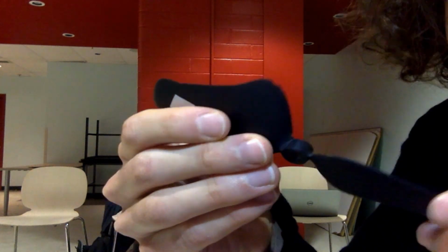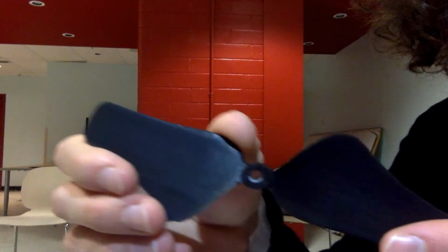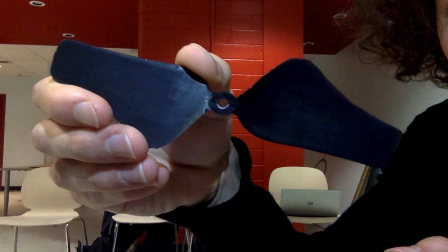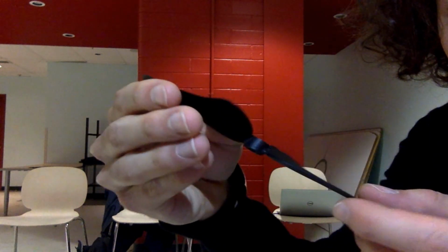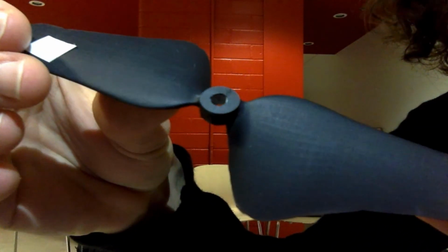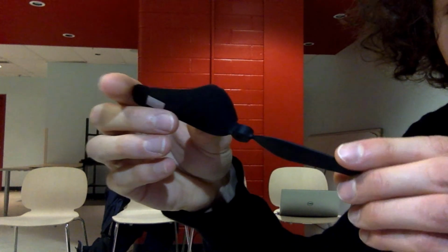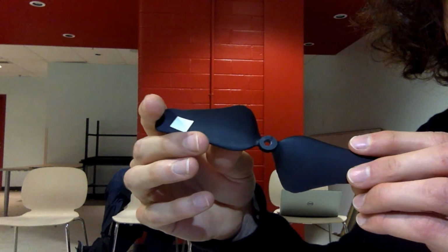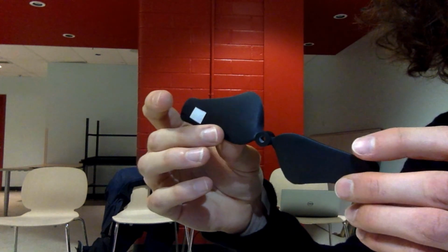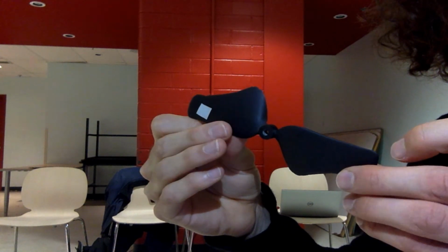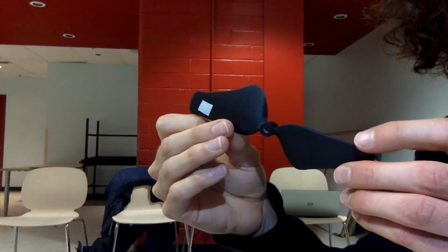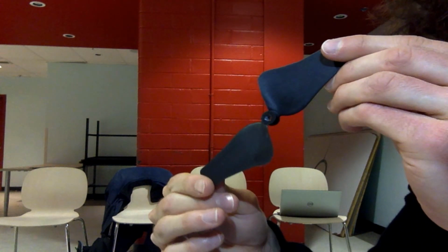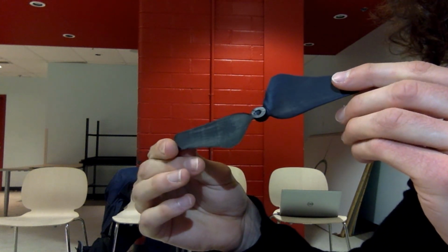And also, in the mounting hole, we can see that it is, first of all, much larger than was designed for. This is because during the 3D printing of the part, this section of the part was filled in instead of being an empty hole, which required some drilling and filing to make it able to fit the mounting screw of the motor. So obviously this caused the hole to be a little bit eccentric, which introduced eccentricity in the rotation of the propeller and also had an effect on noise and the efficiency.